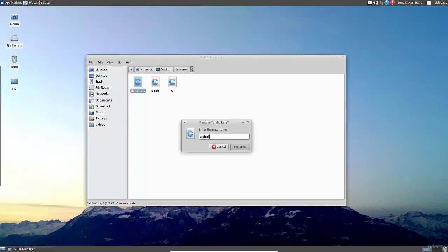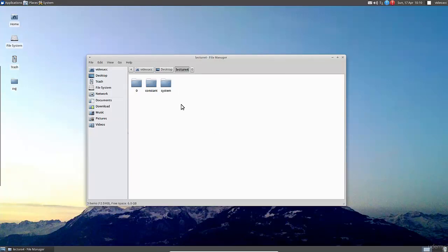Alpha is the ratio between two fluids, so it's from 1 to 0. 0 means fluid 0 and 1 means fluid 1. So look in the constant folder. Let's delete the boundary file. Okay, system, setFieldsDict.